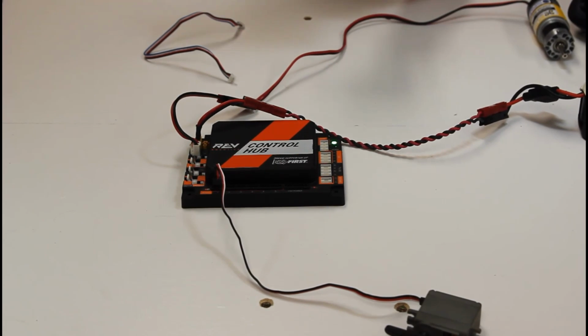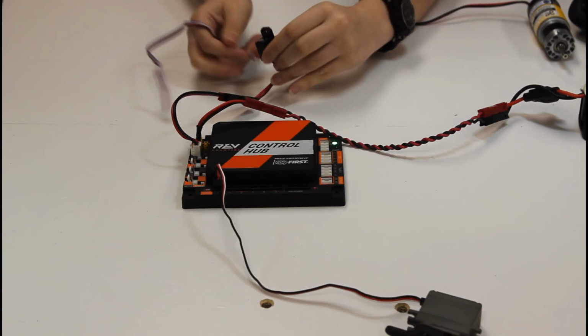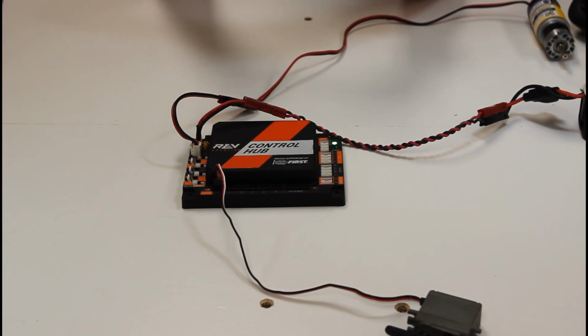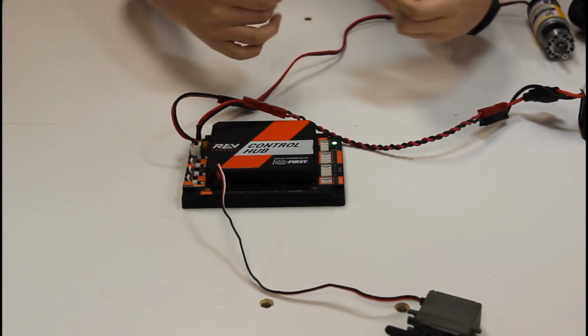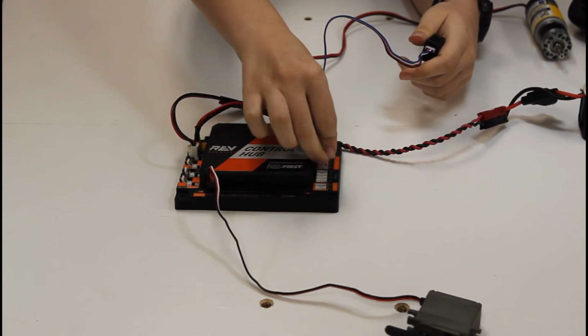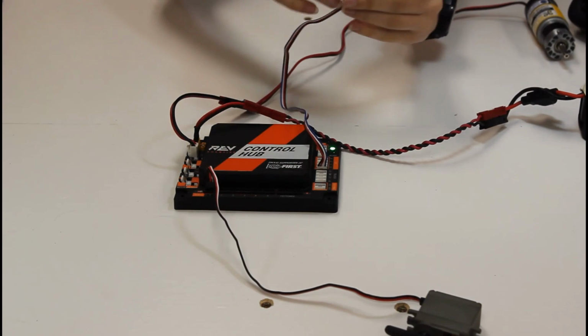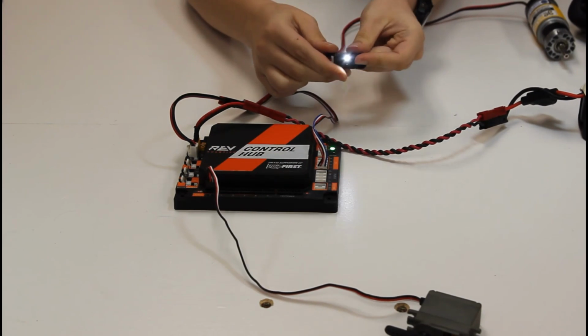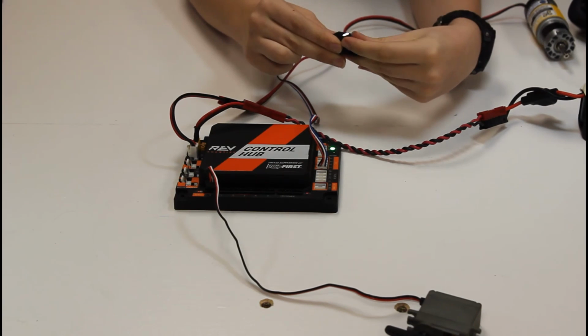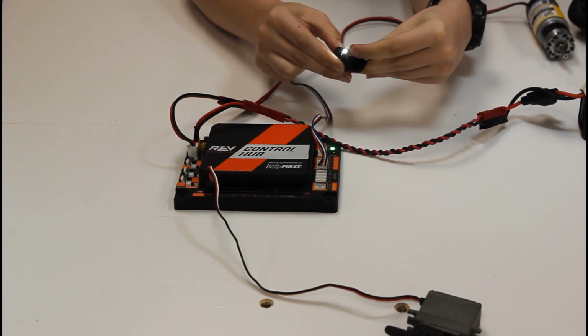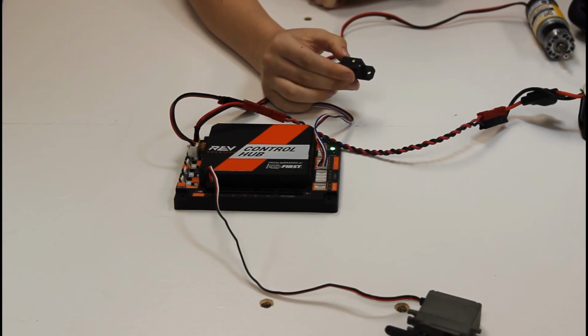So, now we'll take a Rev color sensor and an I2C cable, plug the I2C cable into the color sensor and into one of these I2C ports. Now your color sensor is plugged in. You can use this switch on the side right here to turn the light on and off. Now let's open the config to get this set up.